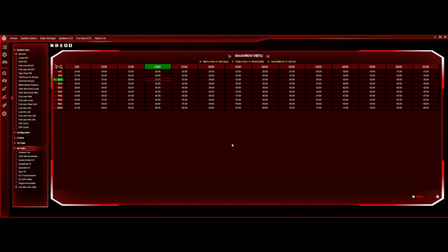You can connect this to your ECU on the laptop, and you can actually monitor live while you're doing this. And you'll see how the engine reacts. You'll see your actual AFR on your monitor, and if it goes up or down, and you can see that.